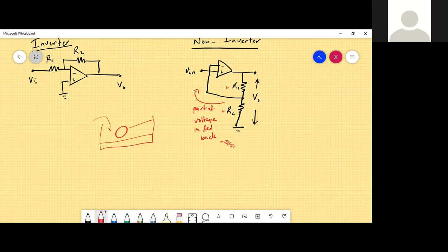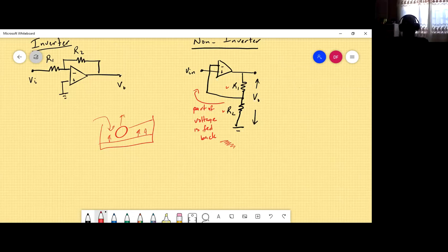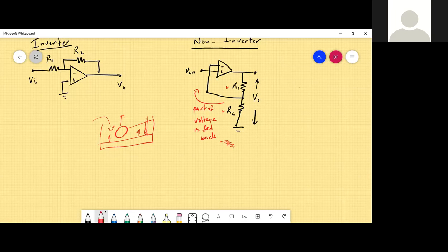Sir, as the water fills up, the ball rises and then it's going to lock off the flow of water. Okay, so you're going to lock off the flow of water. As the ball rises, more and more it locks off the flow of water, so the flow of water gets less and less until it turns off when it reaches the level.